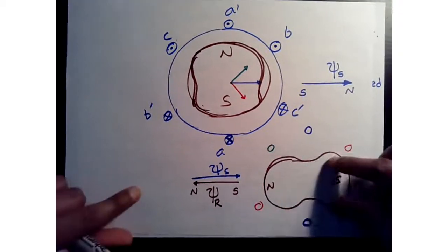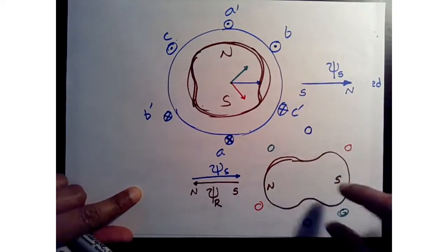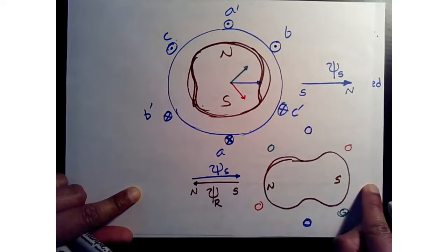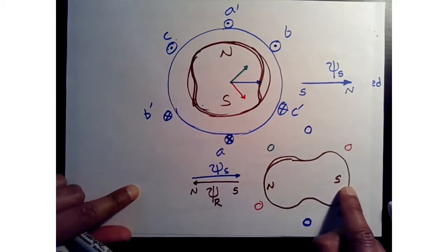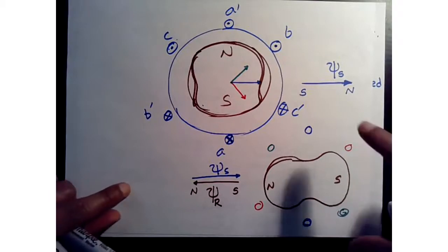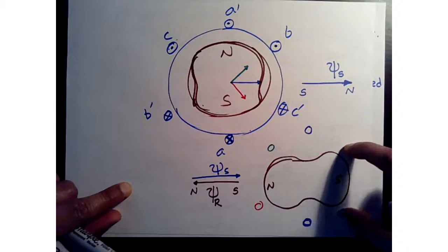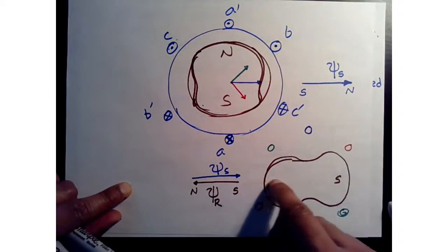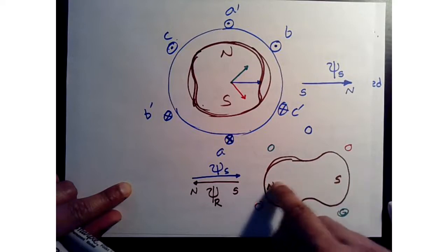And now by using this DC current, we have forced the rotor to align in this direction such that when we measure inductance from A to B and C, we are measuring the inductance considering the material along this direct axis.